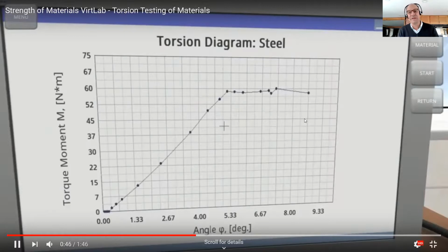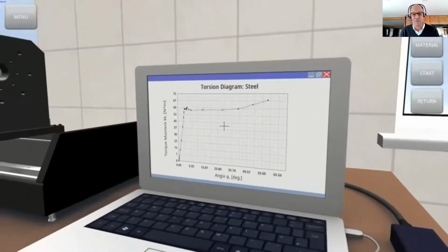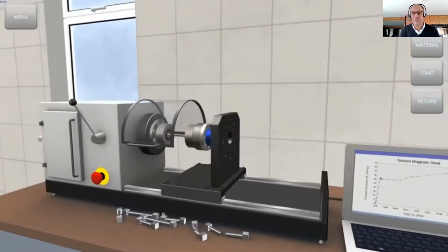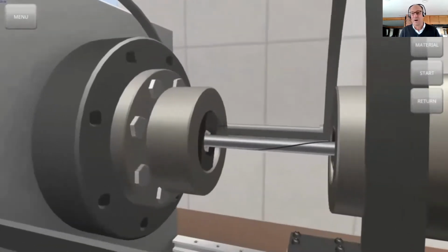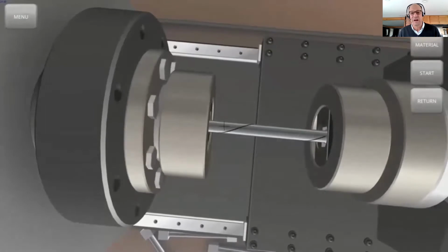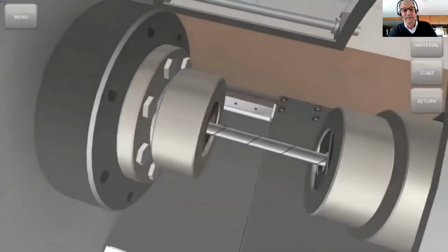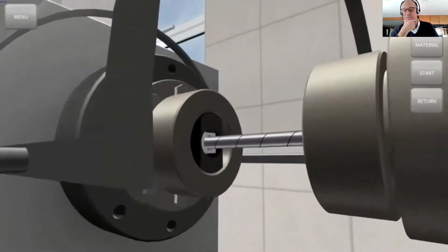All right, you can see now that this is extending into the plastic region, which is something we're not all that concerned about. And it's going to keep twisting and twisting because, thank God, ductile iron twists and twists. Otherwise, if we were involved in a car accident, that front bumper and front fender and stuff would not keep collapsing. Remember the straight line that we had on this, and you can see that it's twisting, twisting, twisting. That's quite far.